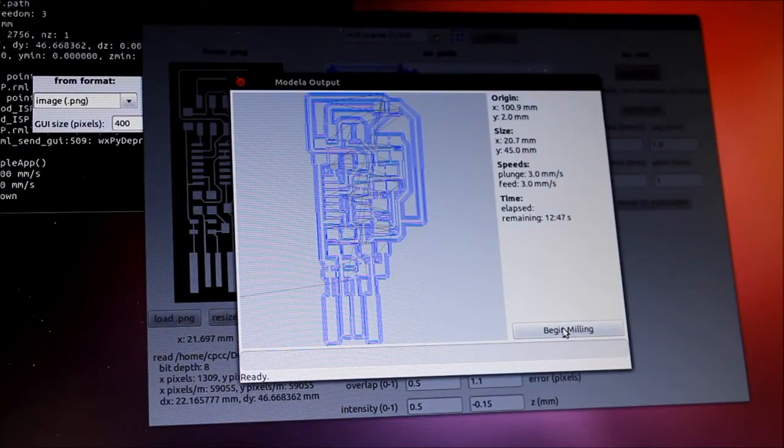That's not very useful if you're breaking things. So I suggest turning the power off on the machine if you notice that something bad and dangerous is happening. Then you can abort. Just know that when you abort and you close this window, the drill bit will actually go back to the 0 position. So you have to go to the other window and click Move to X min, Y min, and then send it again. Then you can mill from the same place, hopefully without damaging anything else.